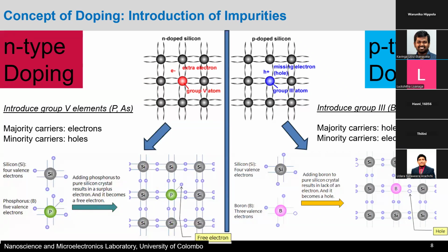So, for example, if you want to dope a silicon wafer N-type, then what you do is you bombard the silicon surface with group 5 atoms like phosphorus or arsenic, right? So this atom would then come into the silicon lattice, right? Usually silicon is connected to 4 other silicon atoms in the crystal, in the lattice.